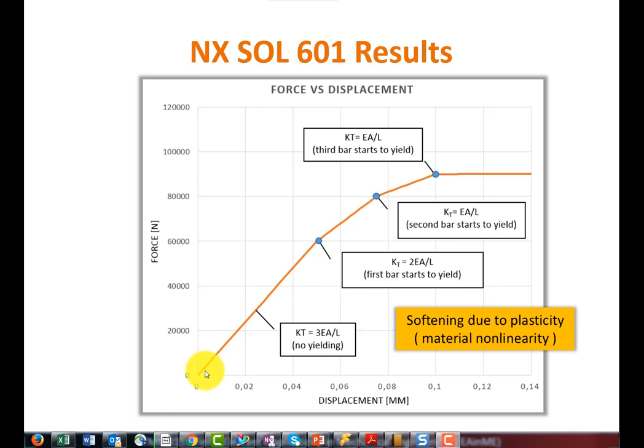And that's also the reason why we applied deformations here incrementally instead of incrementally applying a load. Because if you apply an incremental deformation, you will get results for each step. However, if you use force incrementation instead, it will run quite well until you reach this limit point.